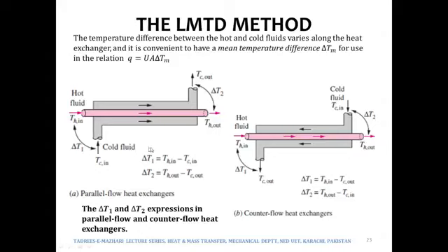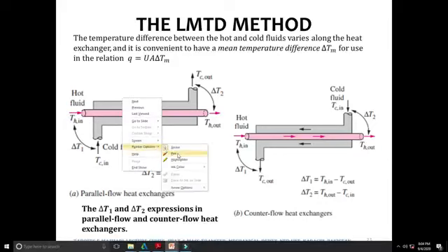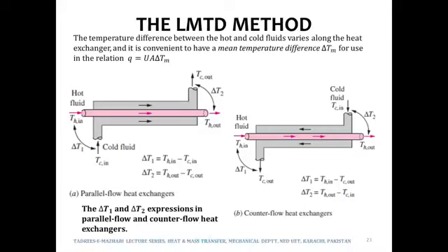In fact, what is happening over here is, for example, this is the parallel flow heat exchanger and this is the counter flow heat exchanger. So at inlet, what is the temperature difference? The temperature difference at inlet is Th in minus T cold in. This is the temperature difference between the 2 fluids at the inlet of the heat exchanger.